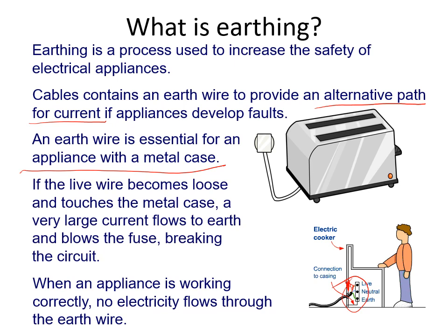Now look at this particular connection here. You can see a connection from the metal casing is going to the earth socket. So anytime a fault like that happens and we say the appliance becomes live, all that charge will flow through this wire to the earth through that earth socket. Okay, so that is what is mentioned here.